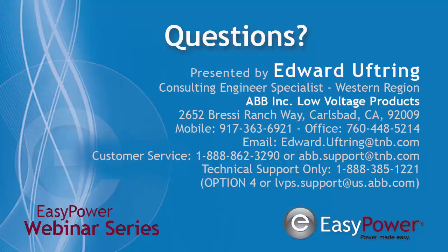What is the typical operating time for breakers on an overload trip? Again, depending on what overload you're looking at, you can set that time delay on the long for whatever you have. Typical, what you're going to see out in the field is in an instantaneous. You're at about around 4 milliseconds. Again, we can do it at 2 milliseconds. It really depends on the breaker that you're using, the overload, and the rating that you have set.